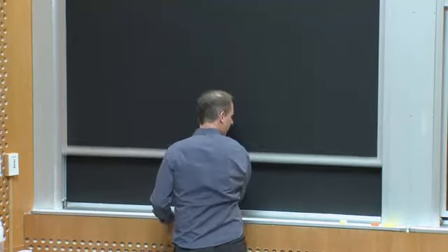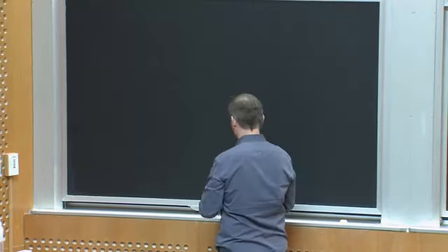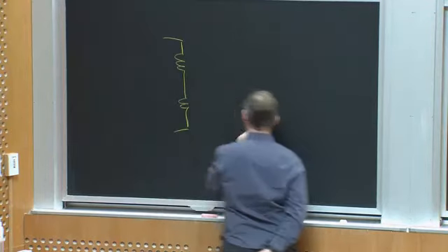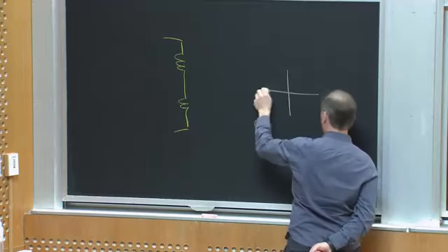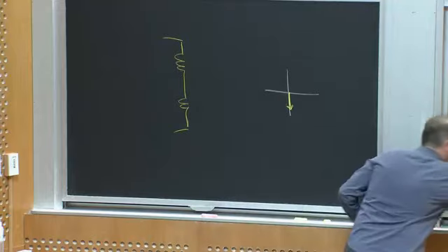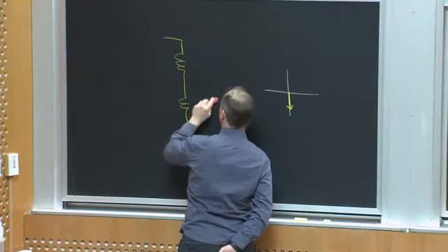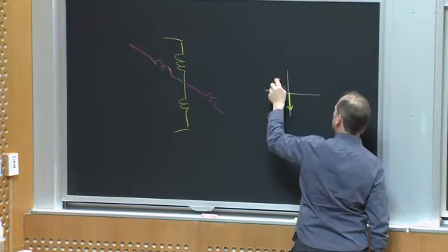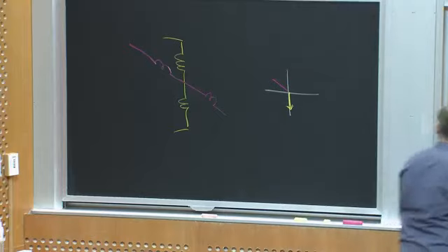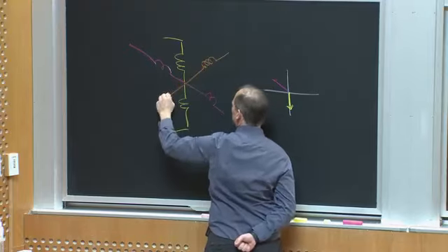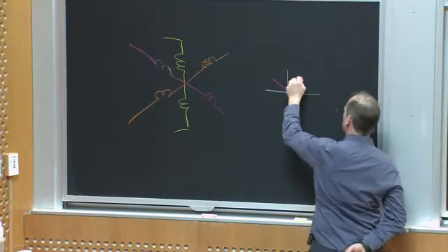So you could imagine putting in, instead of having two that are 90 degrees out of phase, a first set of coils that generated something like this direction, a second set of coils to generate a second direction that was like this, and a third set of coils overlapped in space that would generate a third direction.